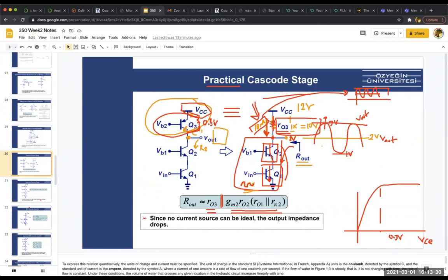That's why we use transistors to implement such big resistors. Putting in a resistor eats your headroom and a lot of power as well. You don't want to put a resistor there and have this entire current go through it and dissipate heat. We hate heat, right? We don't need heat in an iPhone chip or laptop. So we don't use resistors in IC design. That's why we use transistors.